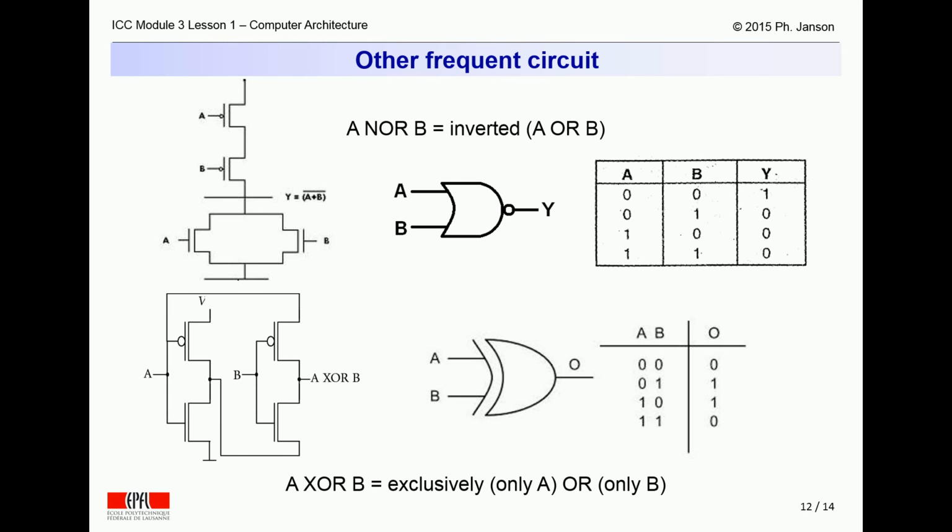The logical XOR function in the bottom part of the slide yields a 0 output whenever both of its inputs A and B are equal to 0 or to 1. When the two inputs differ, i.e. one of them is 0 and the other is 1, the XOR function yields a 1 output. This is what the truth table states, and indeed what the transistor implementation yields. The output will be 0 every time A and B are equal to 0 or to 1.